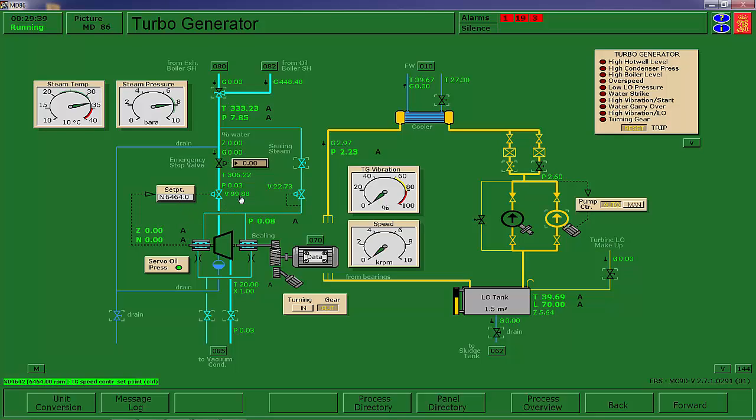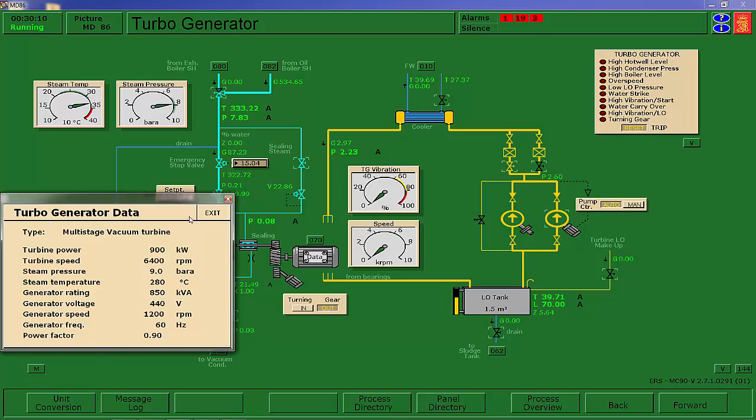You notice the governor right now is wide open. So we are controlling the startup and the speed that this turbine's coming up with the throttle. Now, one of the things, I'm going to go ahead and put 15 in and get it revolving. And you should see the turbine speed come up. One other thing about the Kongsberg on this startup procedure, you can tell that they're motormen and not steam. This is a 900 kW generator